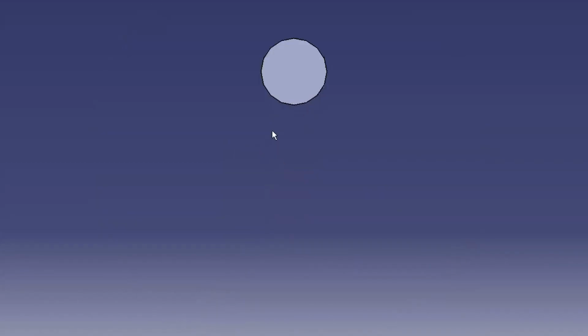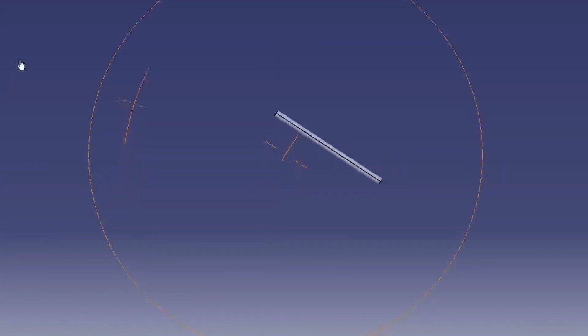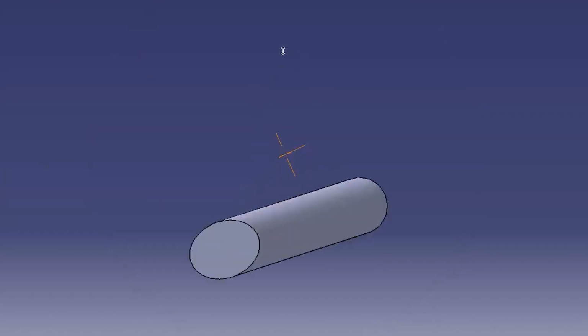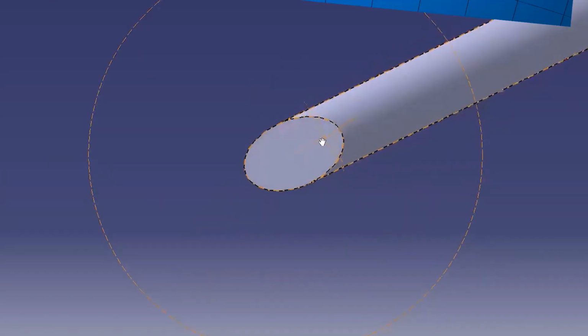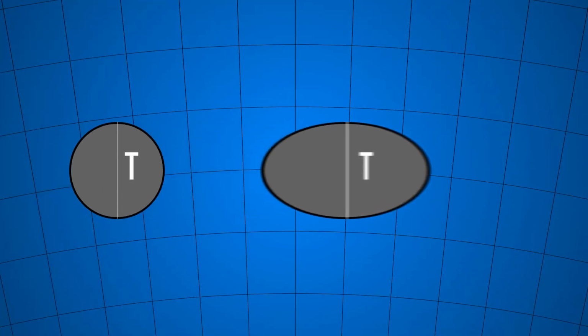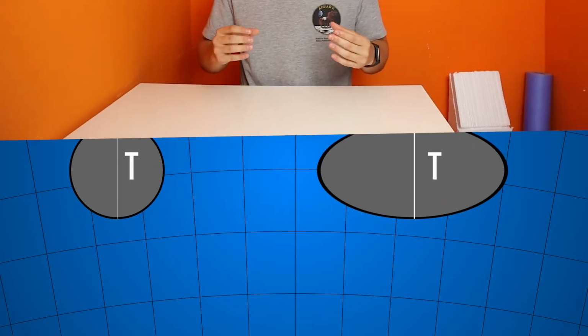Imagine we have a cylinder and the air is passing over it. If the cylinder is straight, the air will see a circle. However, if we now give it a certain sweep angle, for the cylinder, the air will now encounter an ellipse rather than a circle, while the maximum thickness remains unchanged. What happens is that the shape the air sees now has been stretched a bit, so it has more time to adapt to the geometry of the cylinder.